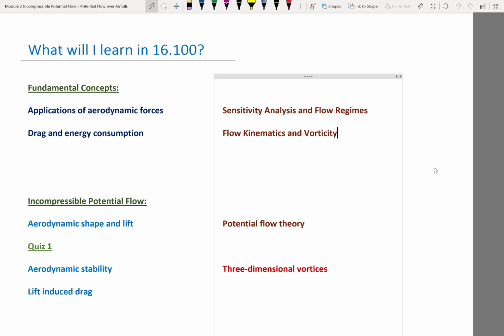And the third fundamental building block was what? Sources or sinks, right? If the strength is positive, we call it a source. It spews flow out of a singularity. If the strength is negative, it's a sink. Basically, it sucks flow into a singularity, like a black hole. All right. So today we are going to see how we use this to build airfoils.